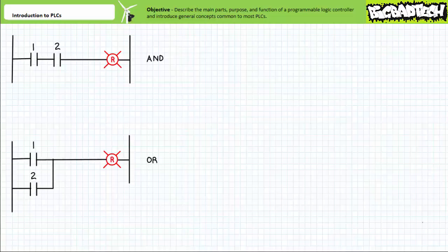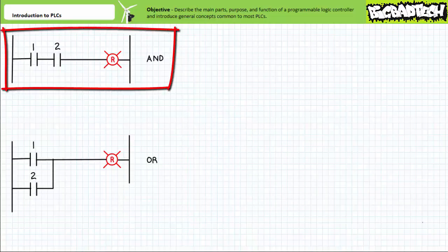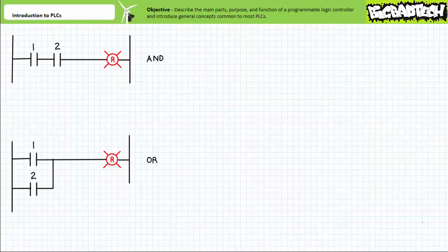If at any point in your education you wish to come back and review this core introductory material, that option is available and encouraged. As we've previously discussed, logical operations of immense complexity can be created by hardwiring input devices, relays, and output devices in a prescribed fashion. The classic example is the logical AND operator formed by the series connection of two normally open contacts. Contact 1 and Contact 2 must both close to assert the output.